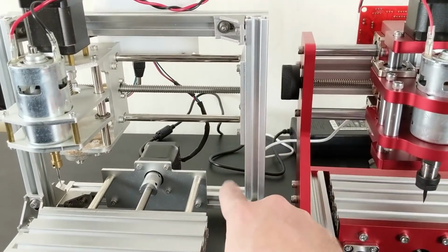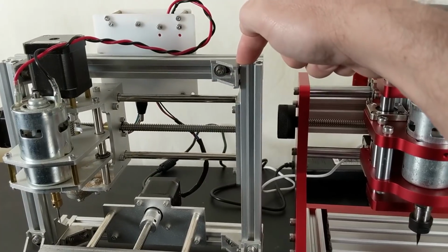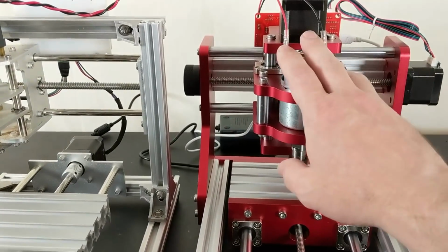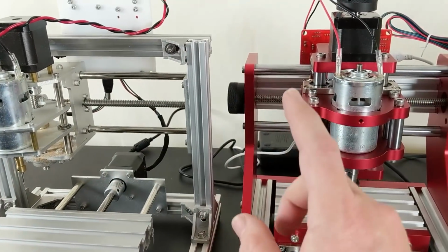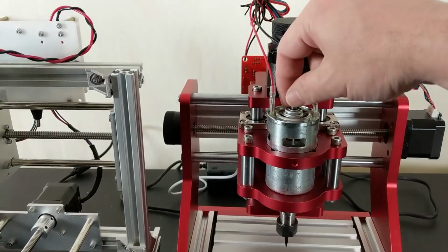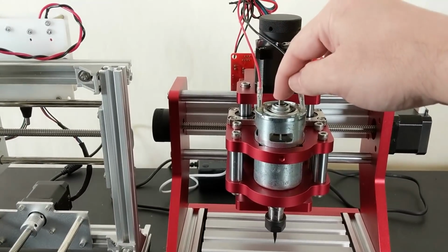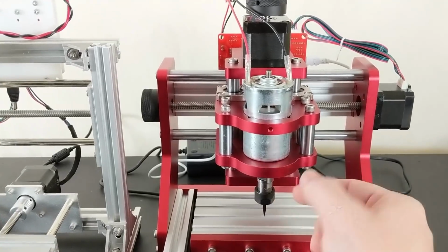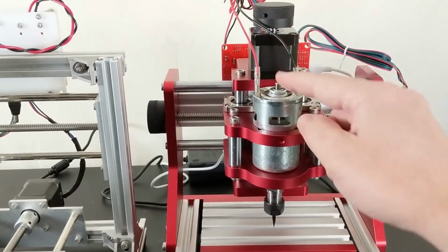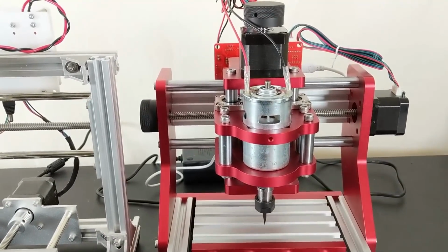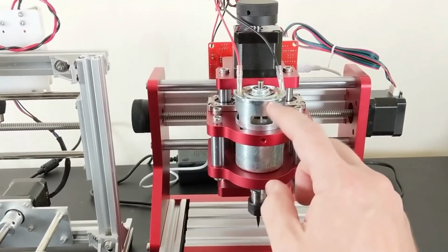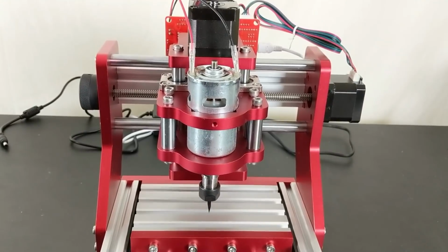So contrast that with this, that's a pinned connection for sure. At the top of that very long run, everything about this frame is stiffer than this one. And what we're left with, the Achilles heel of this machine as far as stiffness goes, is this axle going through the motor. And that is a 5 millimeter axle. And behind this, this bit of plate here is the joint between the collet and the axle. And there's that moment where it can bend. And actually the axle can bend in between the bearing up here and the bearing down there, internally to the motor as well. We'll see what it does once I try to cut with it.